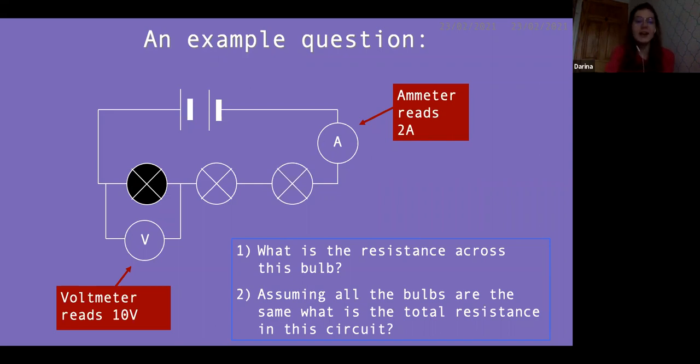Now, also the circuit diagram is the first time you've seen a voltmeter and an ammeter. So I'd just like to emphasize that a voltmeter is connected in parallel. What this means is that there is a separate little branch across the points that you want to measure it over. And this is really important because remember, we said that voltage was defined as the energy change between 2 points in a circuit per coulomb of charge passing through. So the voltmeter is basically measuring the change in energy from this point to this point. That's what that voltmeter is measuring.